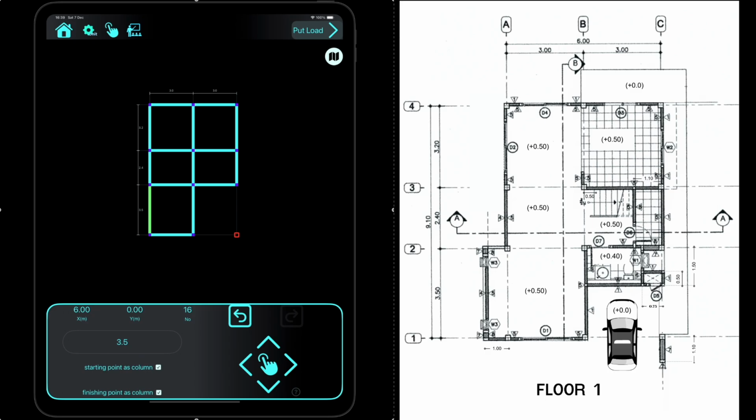Step 2. Every wall position must have a beam to support it, since precast floors cannot bear the load of the walls. And the same applies to cast-in-place floors unless you design the floor to support the wall load. However, in this example, we will not go into that detail. Start by canceling the beam at both the starting and ending points. For the positions where you need to place a secondary beam, move 1.1 meters to the left. Enter the distance and choose the direction to the left, then drag downwards.